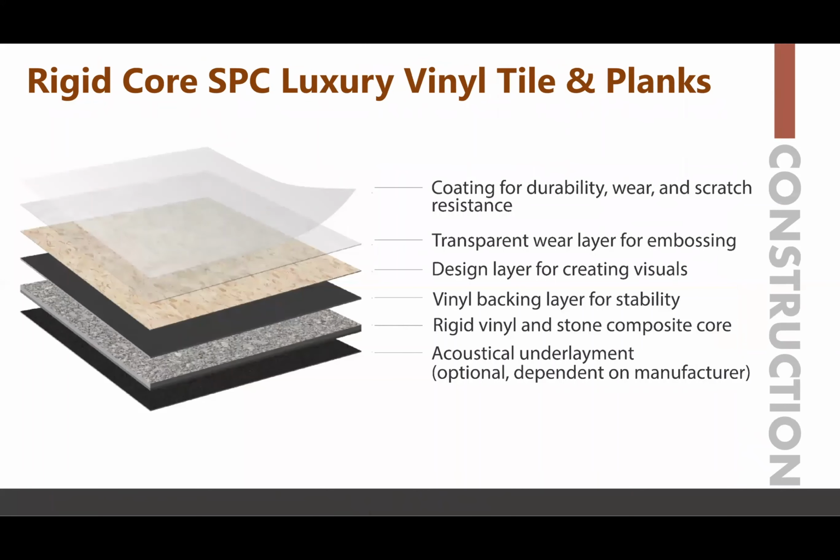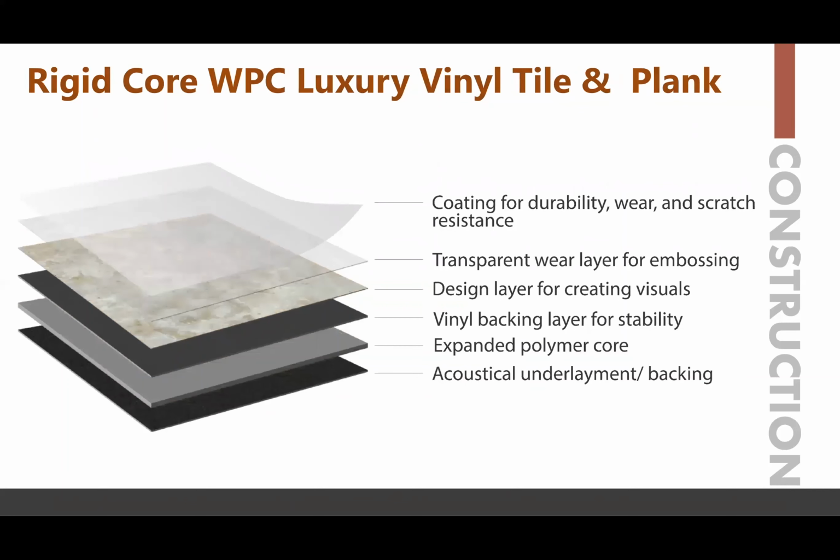So both products are durable and stable. However, SPC luxury vinyl tile and planks is more durable and denser overall due to its limestone composition. Both work well in commercial interior spaces. WPC is softer and quieter underfoot, while SPC offers better resistance from scratches or dents. So understanding your owner project requirements is very important when you evaluate which to use, SPC or WPC.